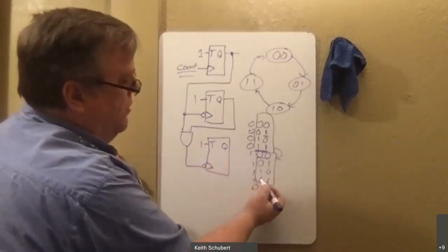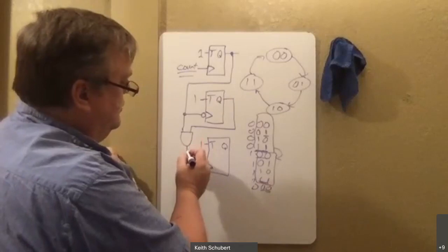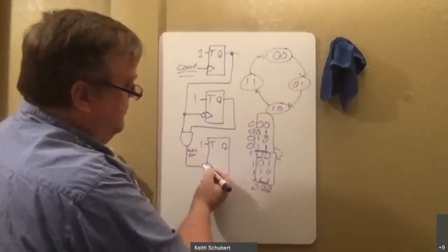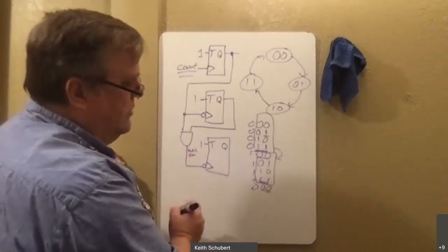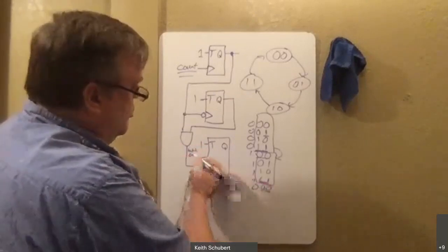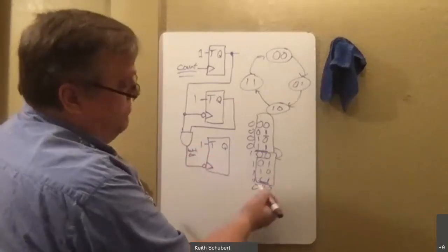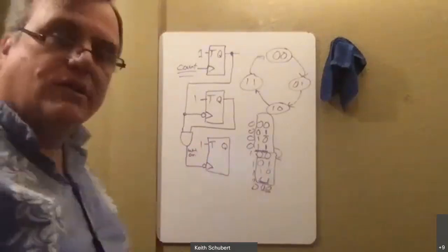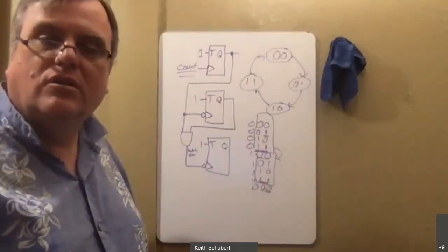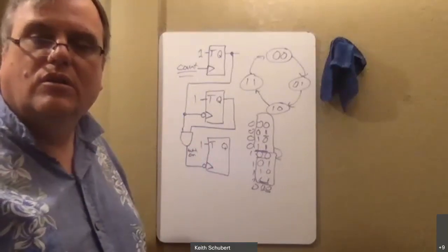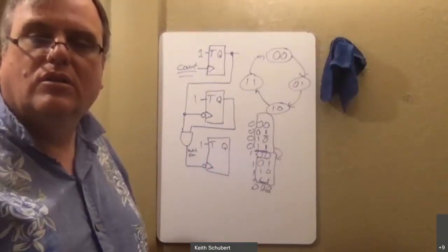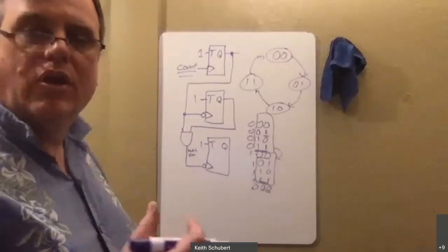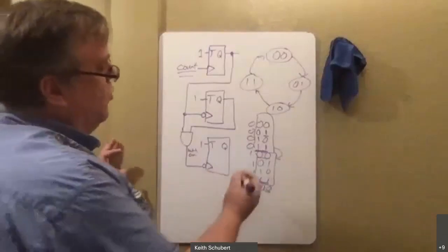And again, when it goes from both on, that's what this is, both on. So when it goes from both on to both off, that's the inversion bubble on the clock. So that will cause it to, again, toggle at that event. All right. Does that make sense? Okay, awesome. Let's just add one more, right?